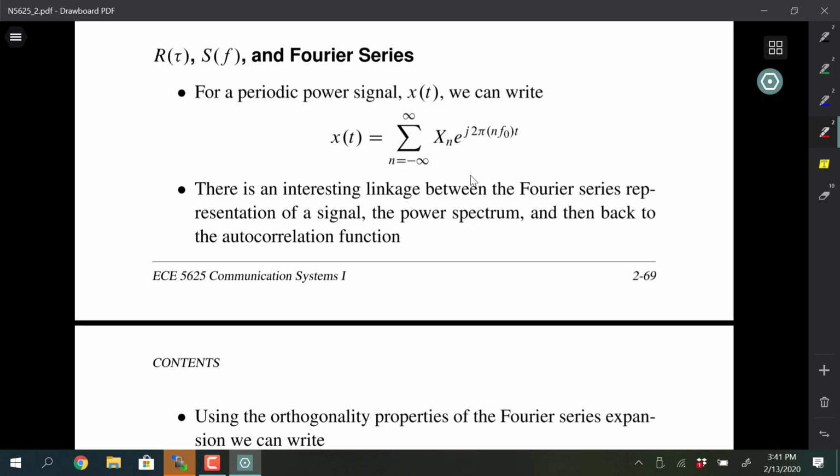I transmit a signal, a piece of that signal bounces off the target, and then I correlate that received signal against the local signal, and that would more formally be called a cross correlation because the signal has gone through space, it's picked up some of the artifacts of the propagation medium and energy reflectance off the target. But then when you cross correlate that, you get a correlation peak, and that peak will take on the delay, the round trip delay from the transmitter to the target.